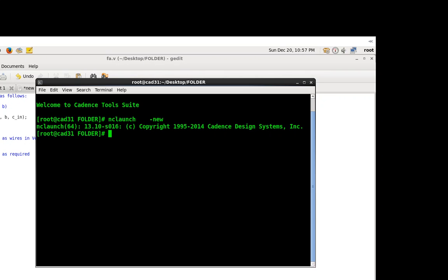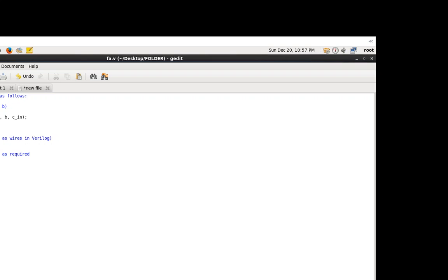So I'm going to do the shift register. I wanted to show how to give the clock signal. I'll copy the design, and here I have a new document. I'll paste it here. Module shift reg, input clock, input clear, input shift, input load, input dn, input si, output register declaration, and here we have the always block, if clear, dout equal to, okay, and we should enter some values. Okay, so its comment is there.